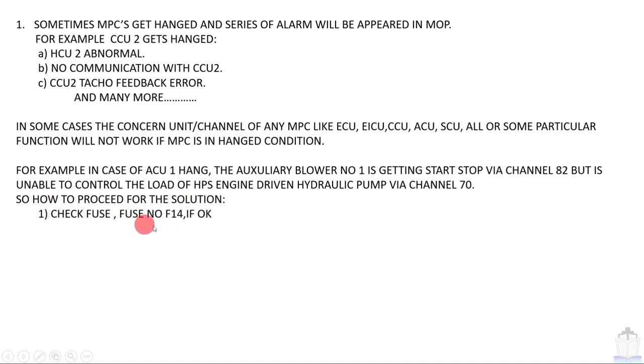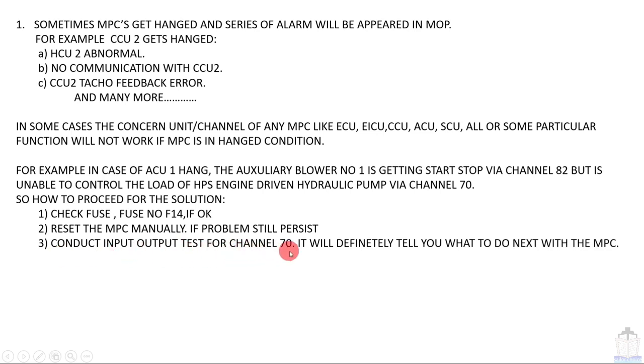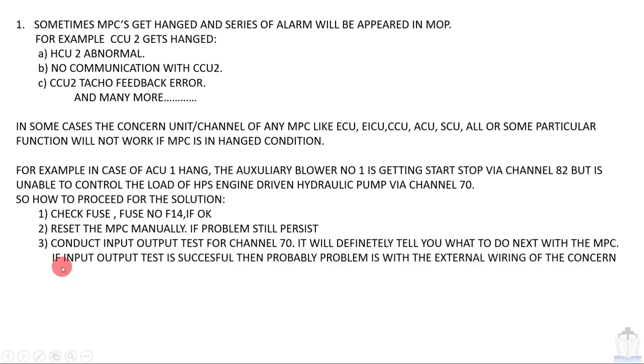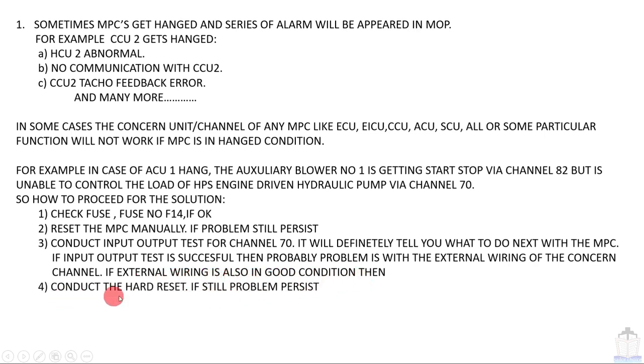First, check fuse number 14 if okay. Reset the MPC manually if the problem persists. Conduct the input output test for channel 70. It will definitely tell you what to do next with the MPC. If the input output test is successful, then probably the problem is with the external wiring of the concerned channel. If the external wiring is also in good condition, then conduct the hard reset. If the problem still persists, then change the MPC. This will definitely sort out your problem.